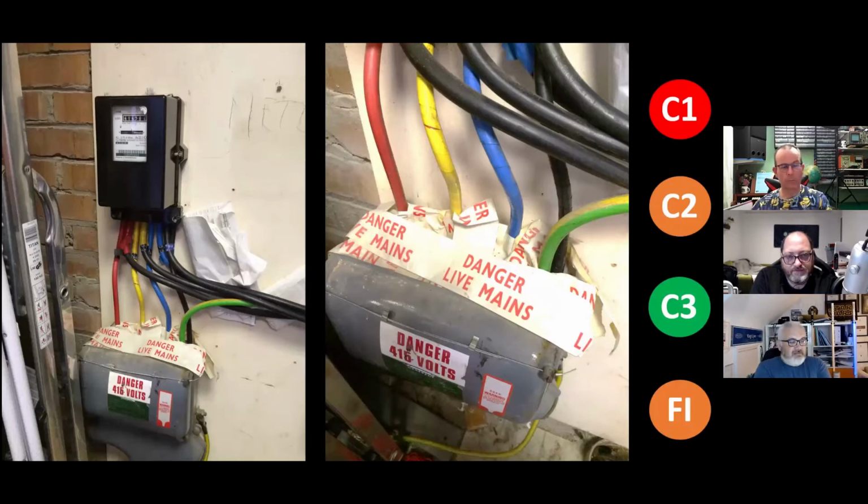But again, metal cutout, if you can probably see there, you've got on the right-hand side of the metal cutout a bolted connection, which then goes down and off with the cable. But you've then got the installation earthing conductor connecting in with the neutral. So what do we think that is?